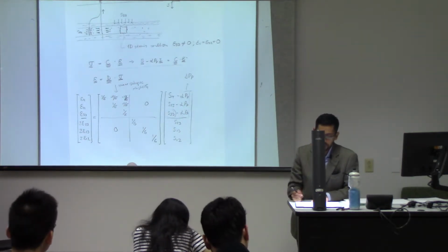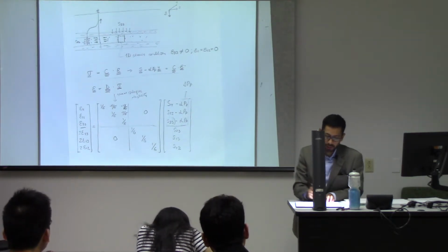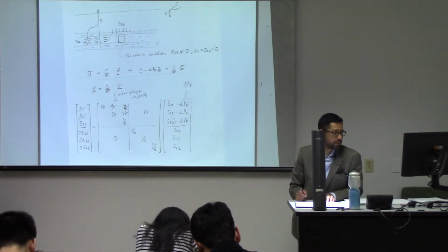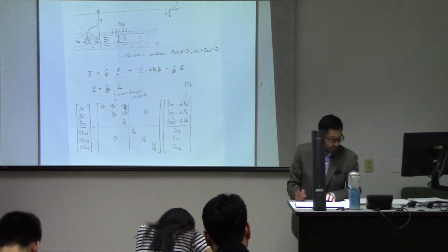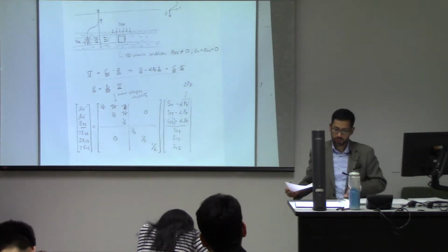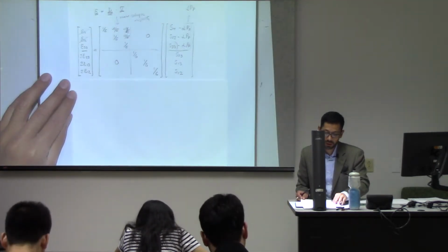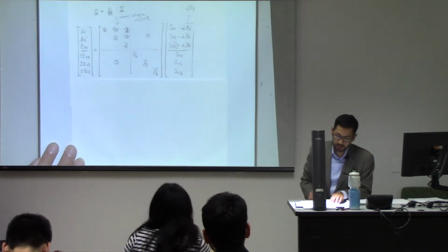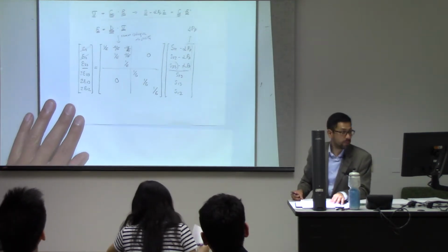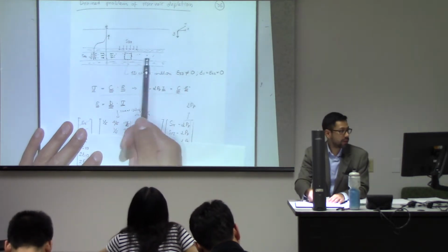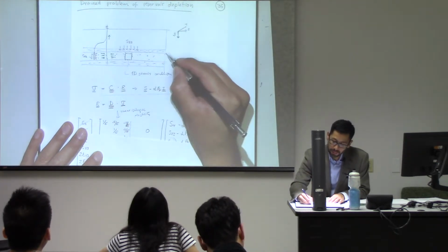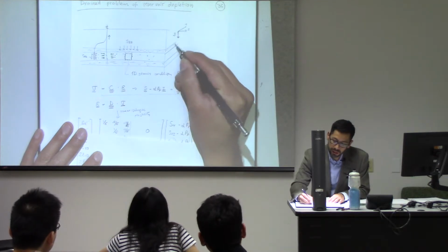So in order to apply the one-dimensional strain condition, we know that epsilon 33 is not going to be 0, but this one will be 0, and that one will be 0 as well. So knowing that, we can write the equations for those. If I just write out these multiplications, I'm going to further consider that in this problem it is laterally extensive in this direction, but it's also laterally extensive in this direction too.